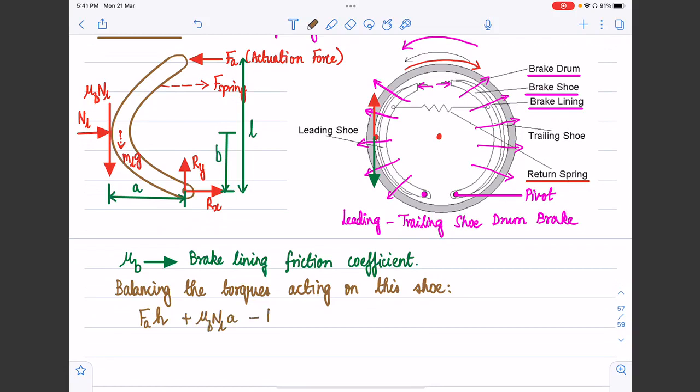And then we have one torque, NL times B, which is the moment due to the normal load NL. And we balance them, so this sum is going to be equal to 0. Please note, in general, I alpha equals tau, the summation of the net torque acting on the system. Here we are essentially neglecting I times alpha. So I alpha is taken to be almost 0.